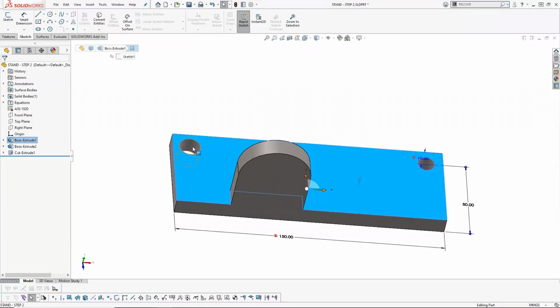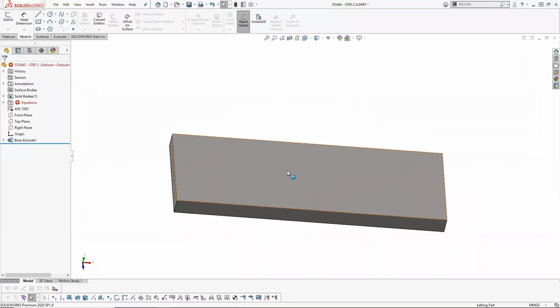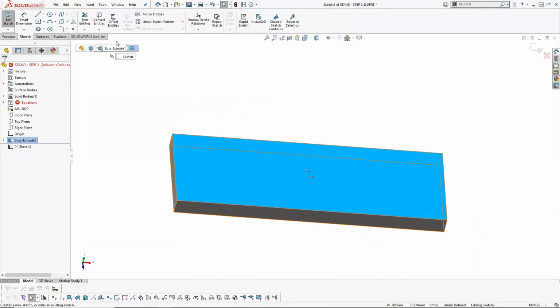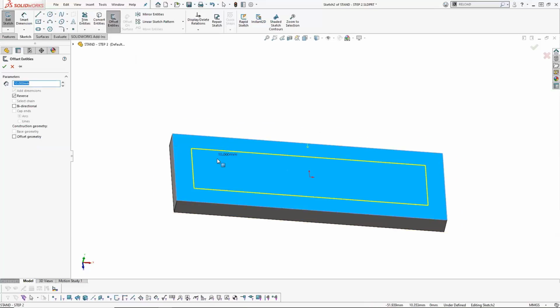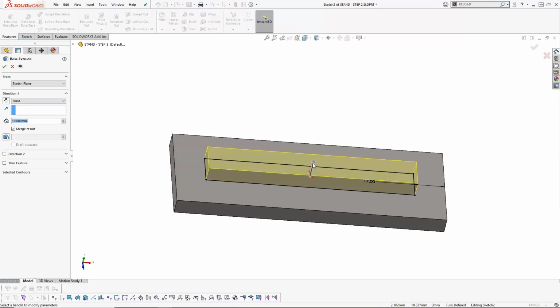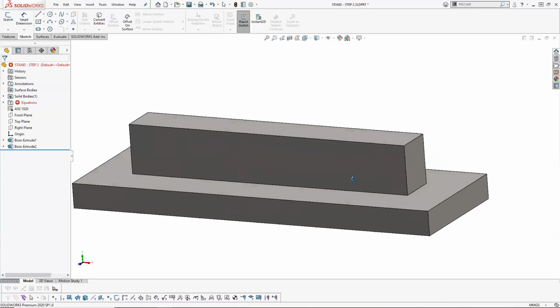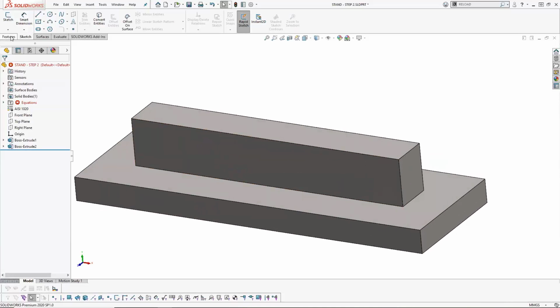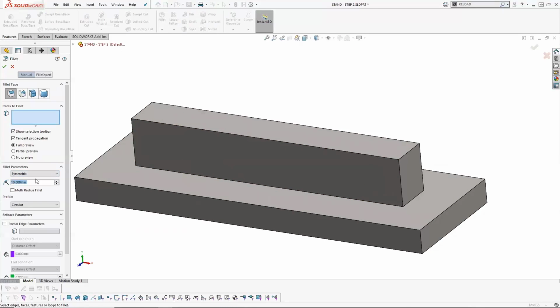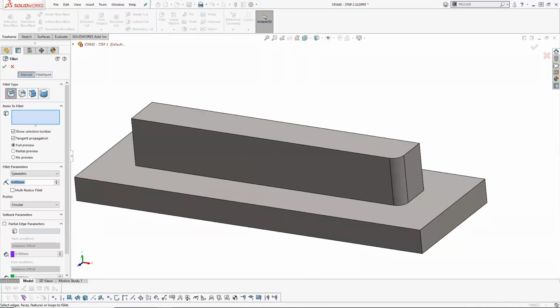If I take this, I'm going to get rid of these features. So I'm going to delete those, and add a new sketch, do an offset to the inside, extrude that up here like that. All right. So when I'm creating my fillets in here, let's say I want to do 4mm fillets along this edge and then 2mm fillets along this edge and this edge.